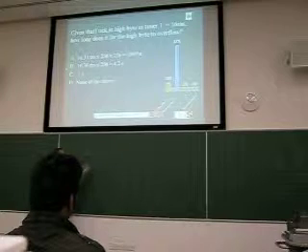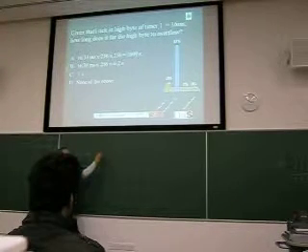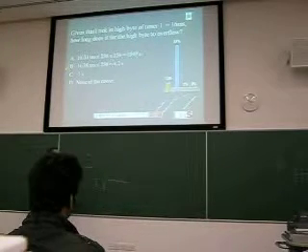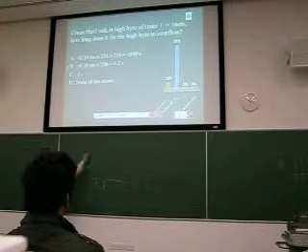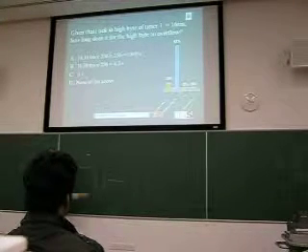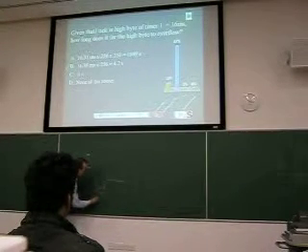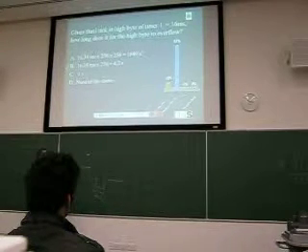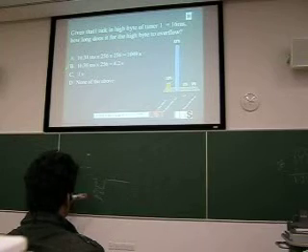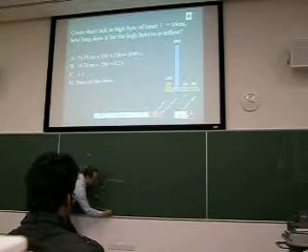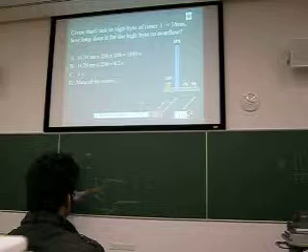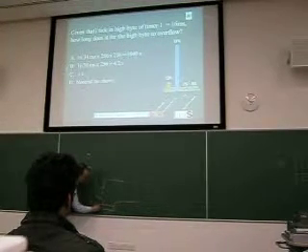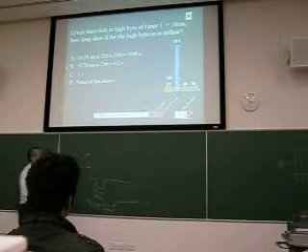Let's say you want to test the length of your button press. If, for example, you want to detect a dot, let's say you can set that to 200 milliseconds. That's your dot. If you want to detect a dash, then you should press a longer press, which is about 2 times this one, let's say 400 milliseconds. Okay, that's a dot and a dash.